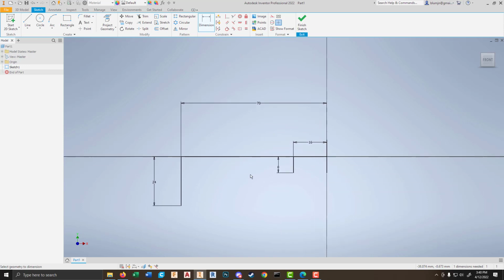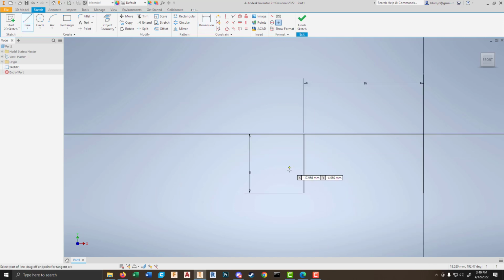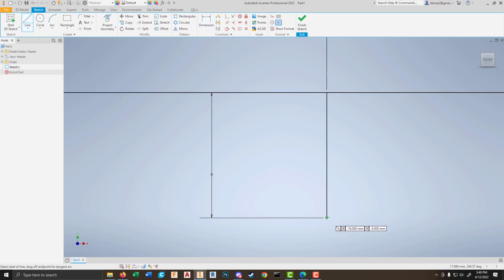And now you might say, looking at this, great, Josh, you've got points. Inventor generally does not do anything with points. You need a profile. And sort of to give us a definition, there will be a quiz later. A profile is a closed geometry, right? So if I do this, that did not close properly, and I can tell it didn't close because I didn't light up green. So see how that point lights up green? That means that I'm latched on. I've got sort of my snap on. And there we go. There's my green snap.